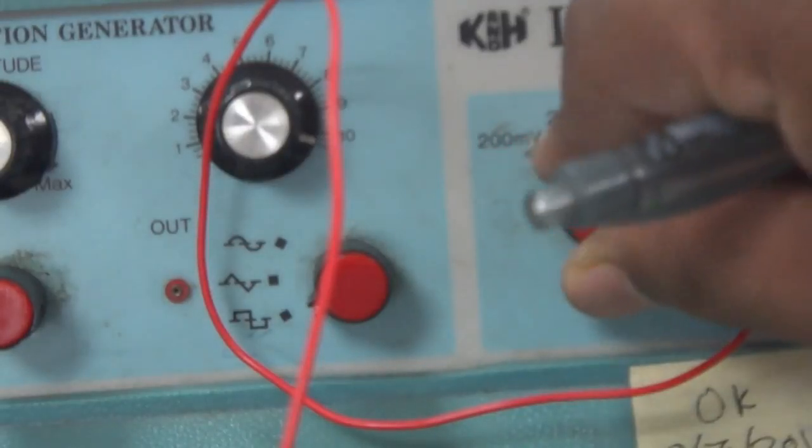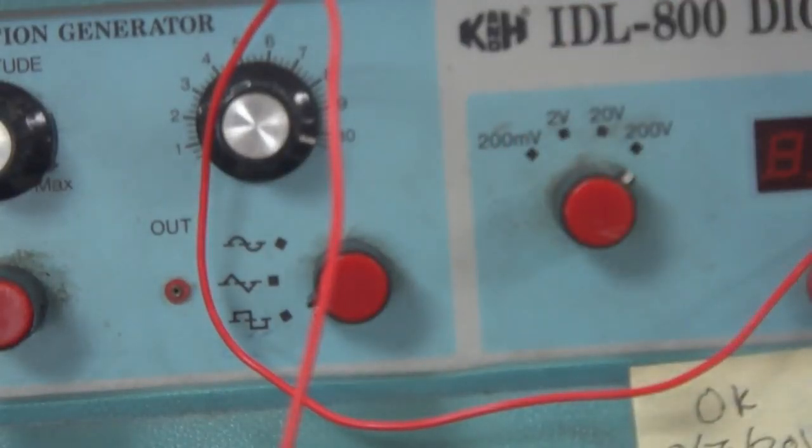So start from the larger scale first, so you know that your voltmeter can handle a maximum of 200 volt. But in this case, I know that my voltage source was only 5 volt. So therefore, I know when doing a series circuit, I will not get more than 5 volt.